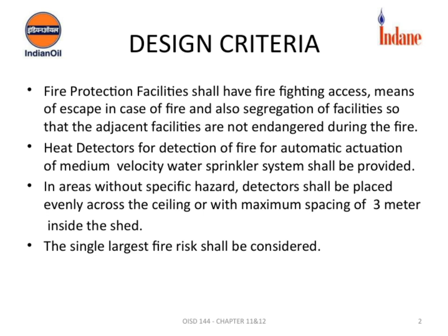Another key point is the use of heat detectors. These detectors are essential for the automatic activation of our medium-velocity water sprinkler systems. They need to be strategically placed to effectively detect fire early on. In areas without specific hazards, detectors should be installed evenly across the ceiling, with a maximum spacing of 3 meters inside the shed. This uniform placement ensures reliable coverage and quick response.